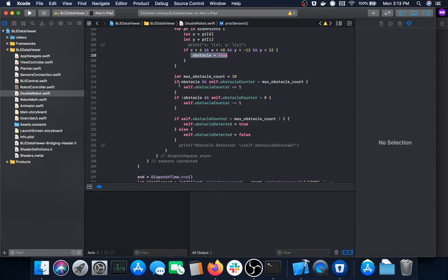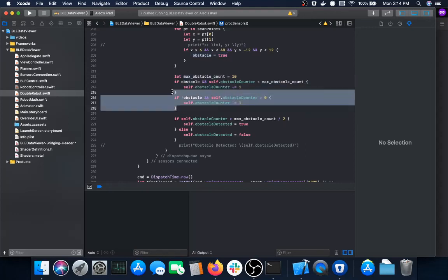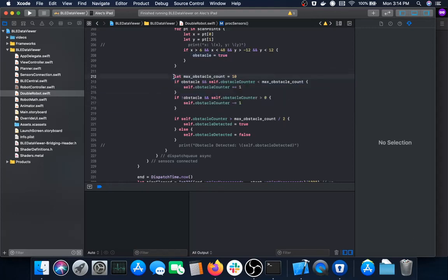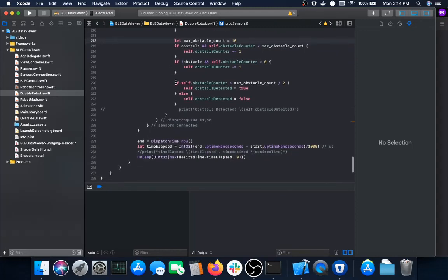And then to actually determine if it's a real obstacle, it averages several measurements over time, to make sure that the obstacle reading is actually accurate and not just, say, a weird reflection or a glitch in the sensor data. So this is making sure there are actual solid measurements, I guess, never mind, it's 5 solid measurements before it actually sets its obstacle detection to true.